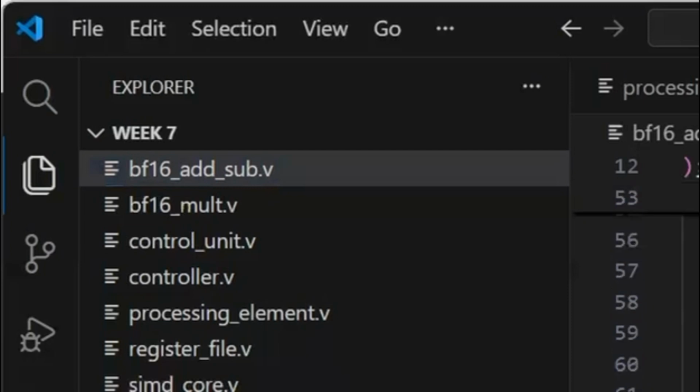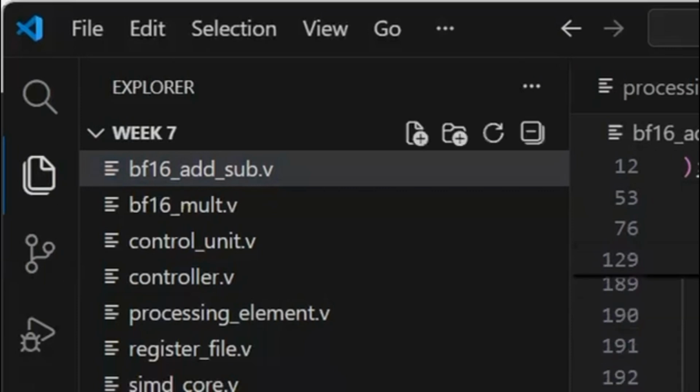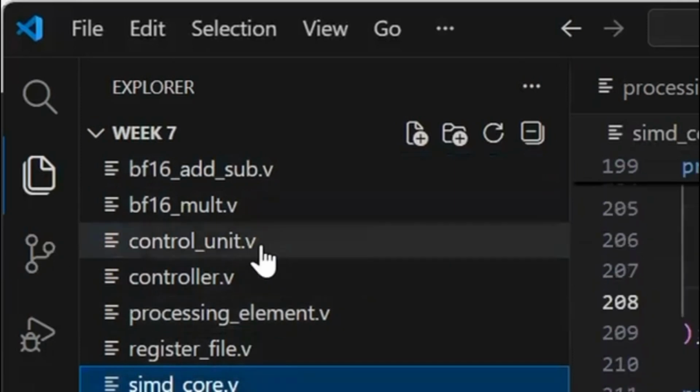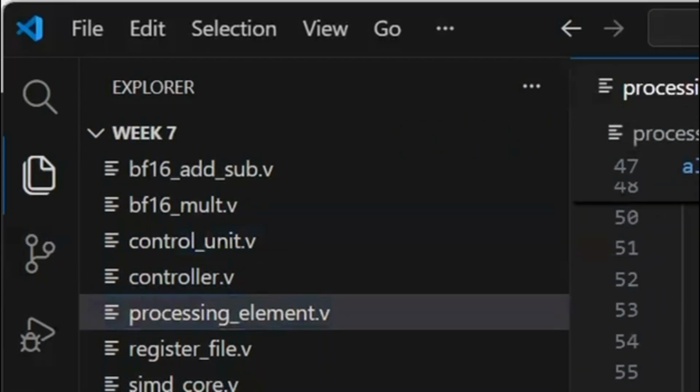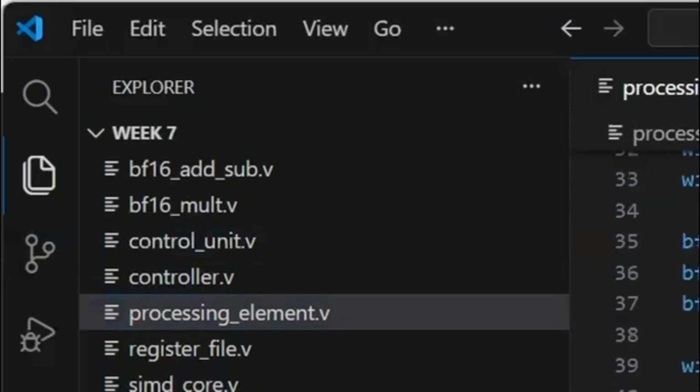The output is also bfloat16. This is similar to the normalization and rounding process, all of that is similar to the multiplication as well. So it's the same, and this is the addition. I've implemented this here, and depending on the opcode, or the data type in the instruction, it will be either bfloat or integer.